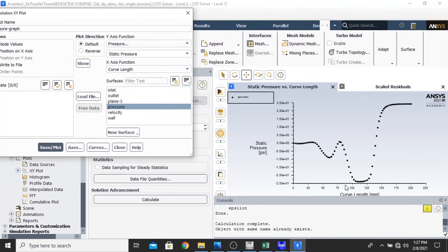So in this position the value of the pressure is negative, so it is vacuum. The pressure is decreasing when it goes through the throat, and then suddenly increases again after it leaves it, going into the diverging part.